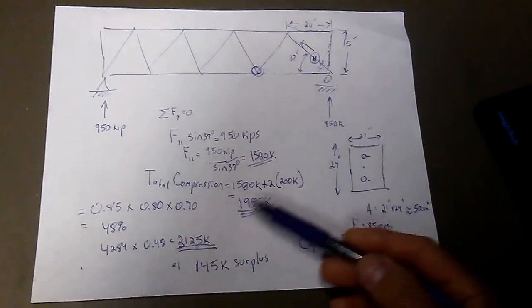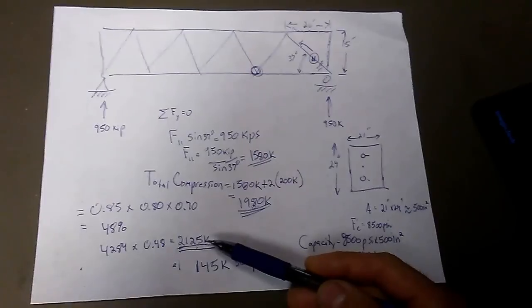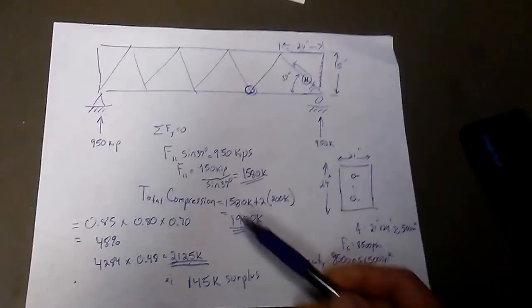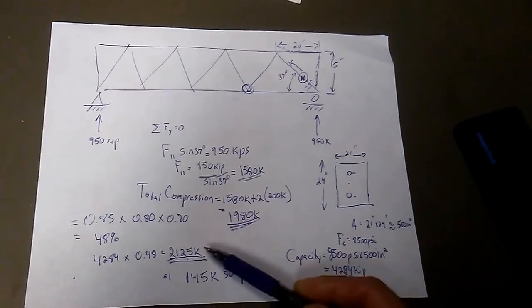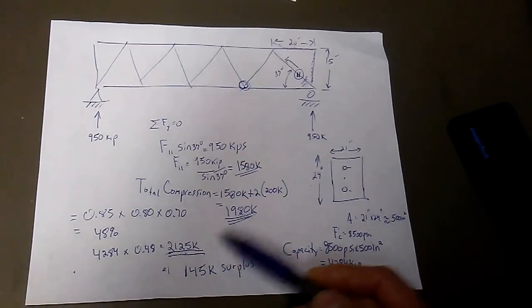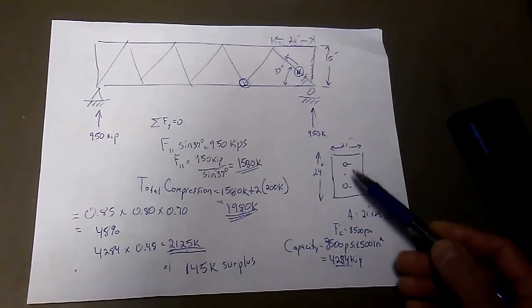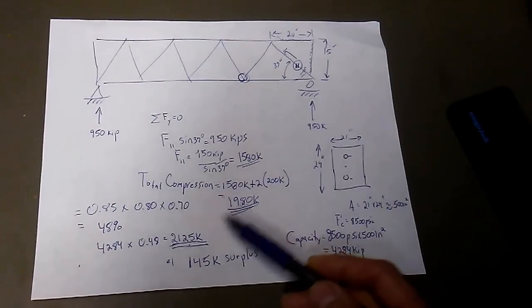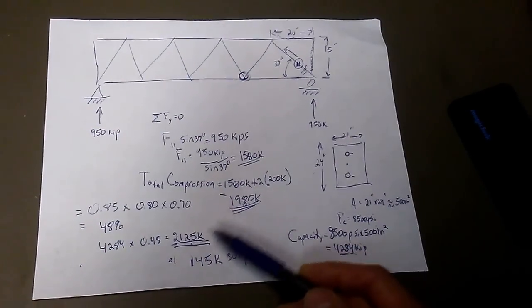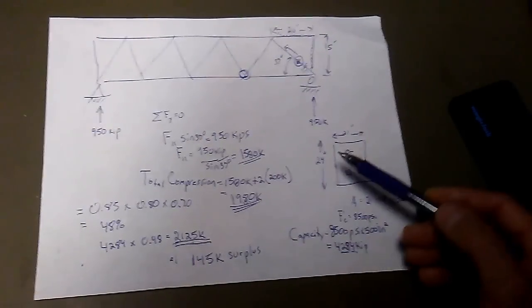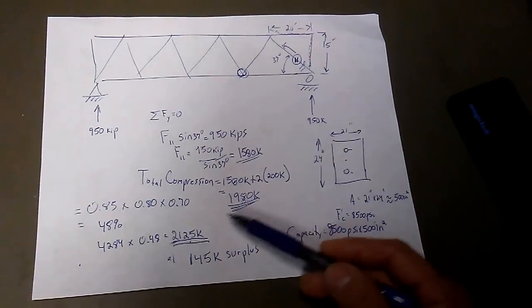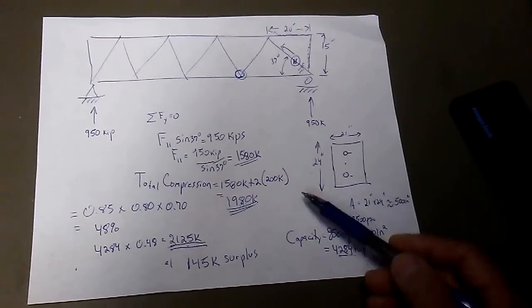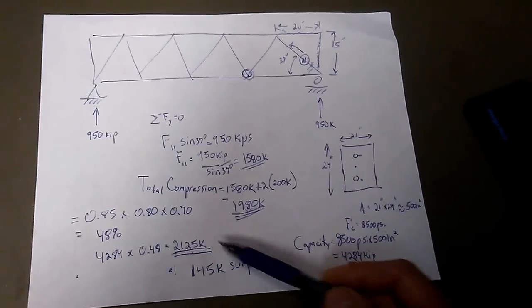Again, looking at the capacity of the member versus the forces actually in the member, the design is sufficient as presented. However, any contractor mistake in post-tensioning reduces your margin for error, your safety factor is reduced, and as stated, there's really not a significant room for error in the post-tensioning procedure before you overstress the member and exceed its capacity.